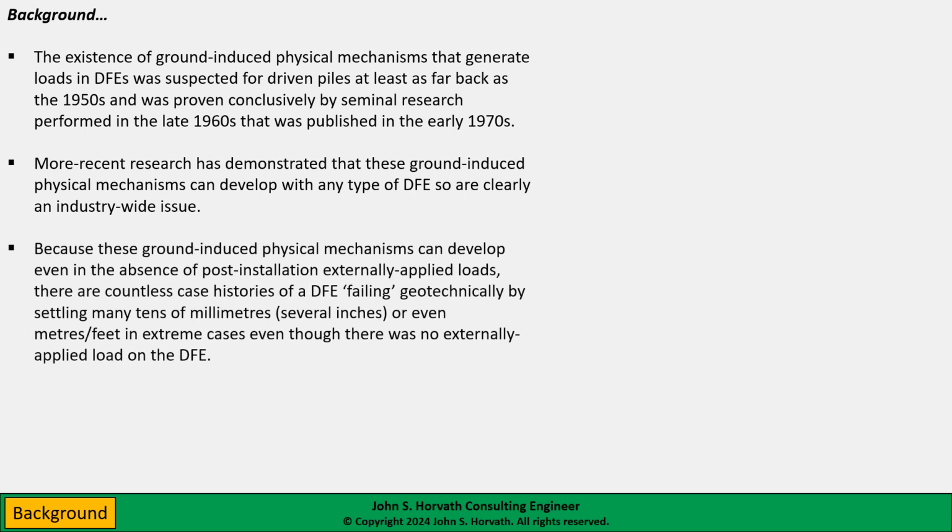So because these ground-induced physical mechanisms can develop even in the absence of post-installation externally applied loads, and this is a very important thing to appreciate, there are countless case histories where a deep foundation element has failed, if you will, geotechnically, and failure in this case defined by settlement of the DFE tens of millimeters, several inches, or even meters or feet in extreme cases, even though there was no externally applied load on the DFE.